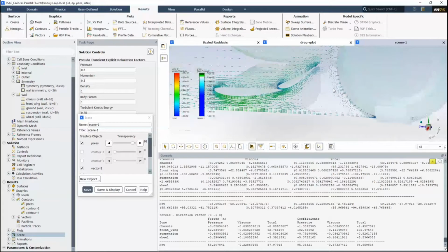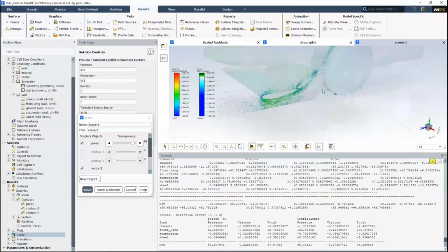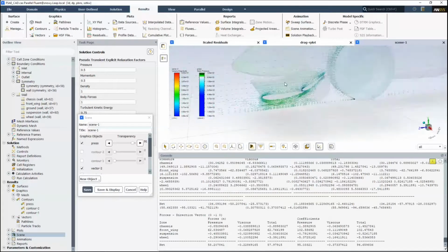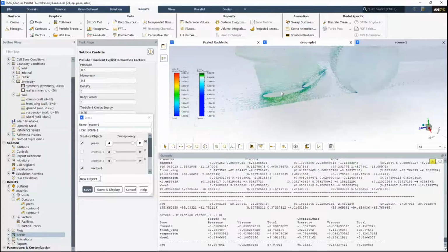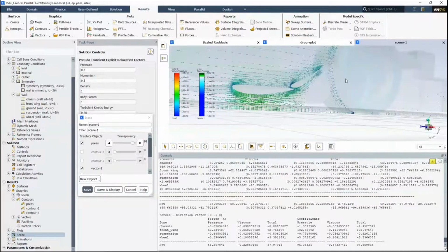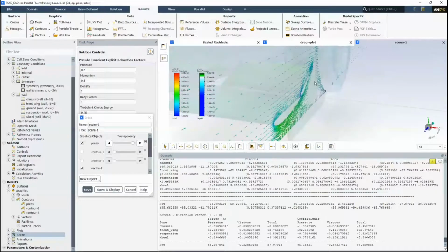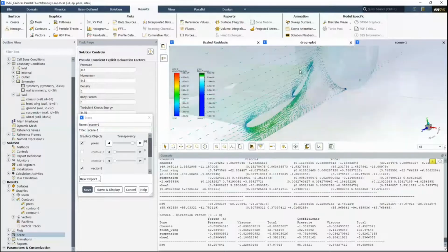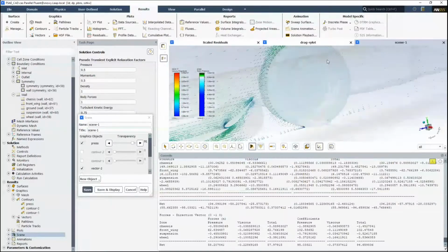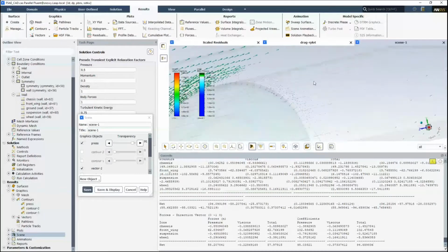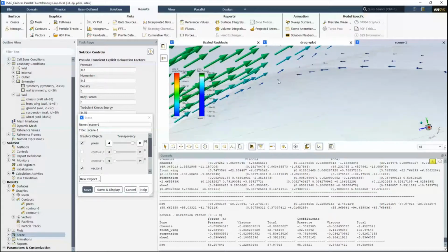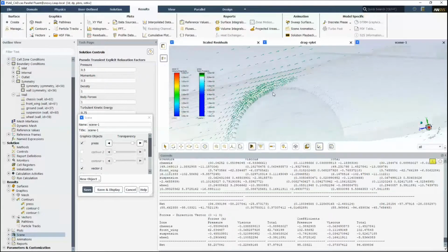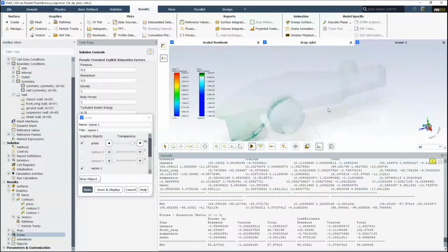It's really hard to deal with these wheels. If you look at the aerodynamics of Formula One cars, you can see that they've got some really crazy end plates that try to capture vortices and throw the flow out away from the wheel. So you don't have as large of a high pressure region in here, but looking at vectors is a really good way to ascertain, okay, where are we separating? We're separating exactly here on that front wheel. And that separation bubble is quite large by the look of it.